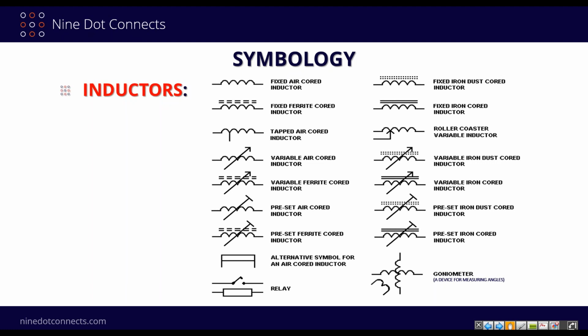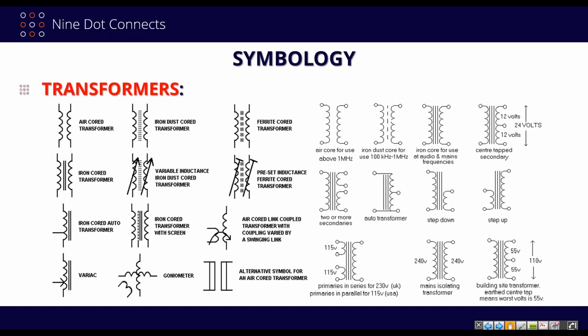The same thing is true for transformers. Generally, all the same information applies. Note that a variac can be drawn with one coil because it is a single winding. However, it is tapped, okay, and it is actually a transformer because it is designed not to store lots of energy. It's designed to transfer it through. On the right, you'll see transformers designed for power. It's customary to show the pinouts of that as the leads coming off from the transformer. Usually the primaries on the left, secondaries on the right. The core is also indicated, and the voltages of the windings are also indicated in each coil so that you can tell what it nominally is supposed to do.